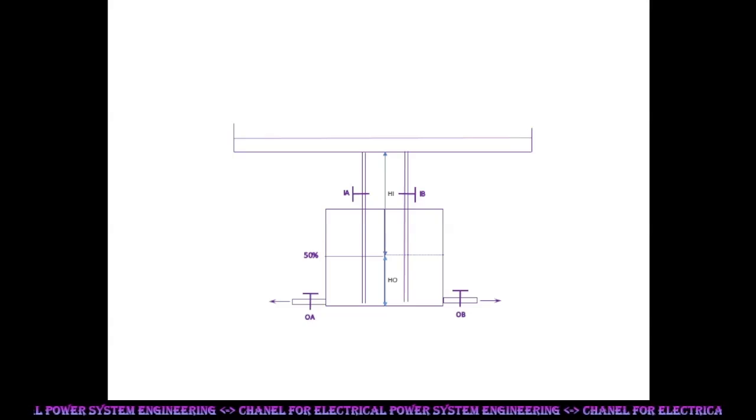A larger power system with more power plants and numbers of load centers has a similar effect. Frequency drops due to load rise in any center. All the power plants are operating in synchronism and frequency is common, so generation is raised at all power plants by the governor system. In the same way, load demand drops at all load centers and the frequency drop is smaller. Therefore power systems are operated in interconnected grid mode for better stability.